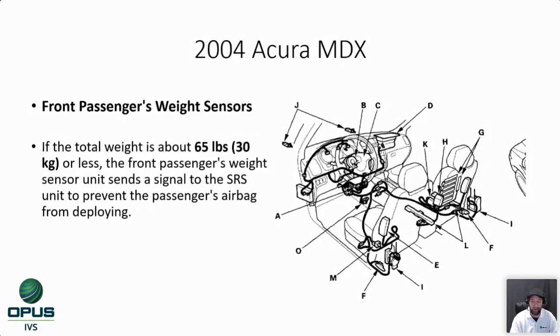I see we have a question in there also from Keith Perkins. He wanted to know when I said replace the sensor or replace the module, whether or not we're replacing with a known good part. The answer back then is yes, you could. These were not programmed in a way that they were VIN locked or anything else. They were part swappable, and through the years, people think that continues on, and we'll see that that's not the case.